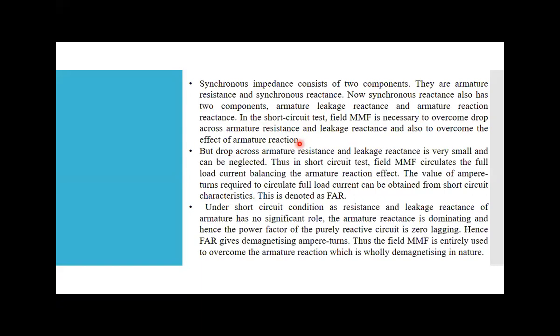So in the short circuit test, we require the MMF to overcome the drop across the armature resistance, to overcome the drop across the leakage reactance, and to overcome the effect of the armature reaction. But the drop across the armature resistance and the leakage reactance is very small compared to the armature reaction. So that's why we are neglecting this drop.